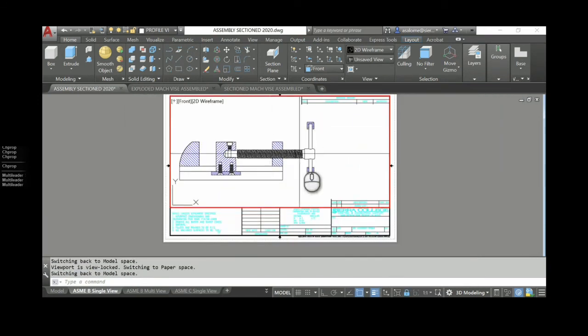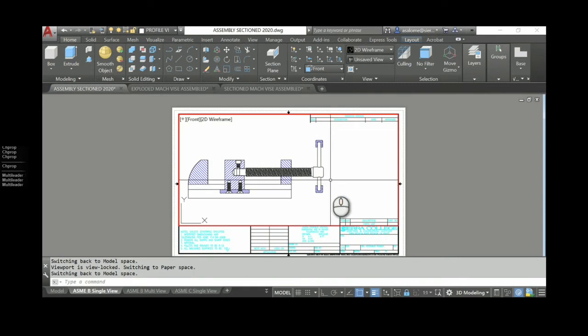And then every assembly drawing has requirements that must be met. So take good notes. You read this in the textbook. You need to have a parts list. You need to have balloons, okay? And you need center lines, so you got to draw your center lines in. Balloons and parts list go together.